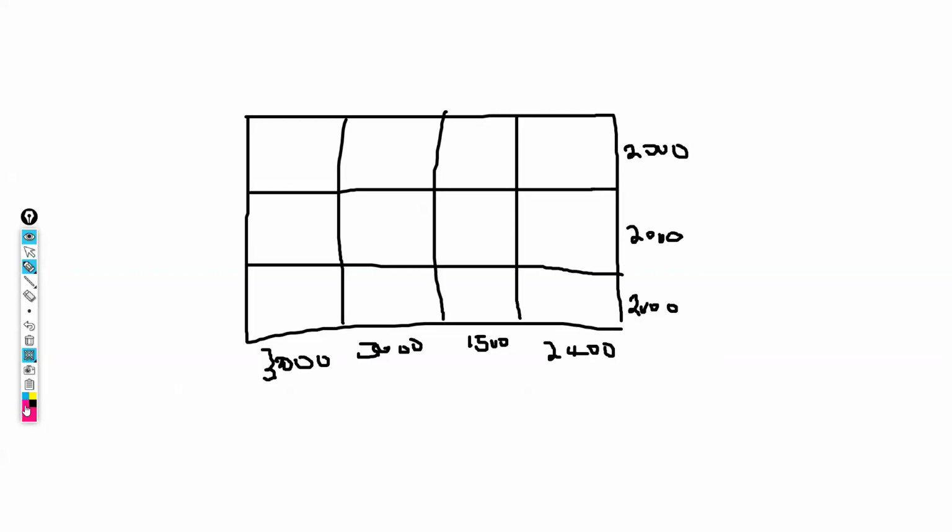And when you are recording those dimensions, you need to stick to this direction and also this direction. It should be strictly from left to right, and the other side strictly from bottom up to top, not coming from the center.